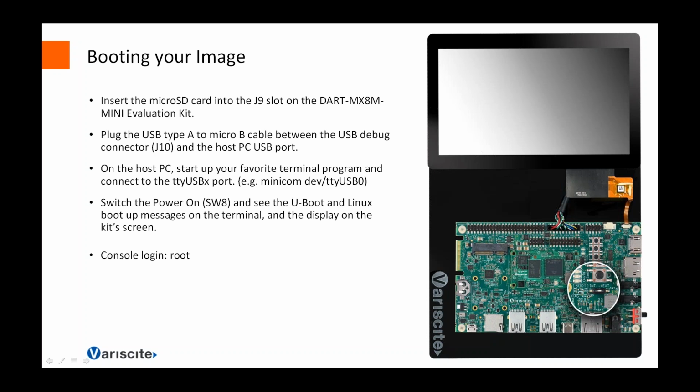Just be careful with the boot switch. All of our SOMs can boot either from an external SD card or from the internal eMMC. If you want to switch between one or the other, you need to change the DIP switch that is controlling it. INT stands for internal, X for external, and that's it.